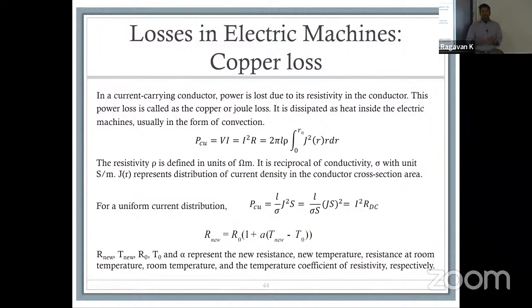And I had to go through my entire calculation to realize that my average current was too low for the frequency I was selecting. So I had a very low frequency. As a result, my current would actually drop nearly to zero and push me into discontinuous conduction. So ideas like that can happen. You can actually introduce an error into your temperature estimation or into your resistance calculation because overall your operating conditions changed.